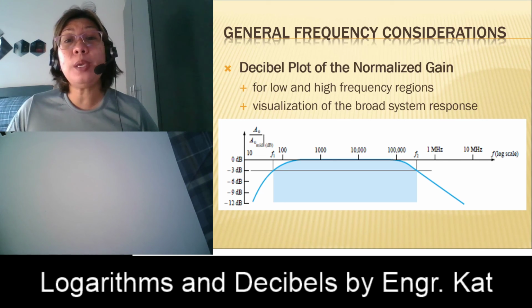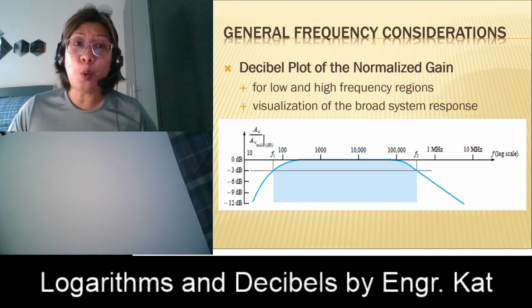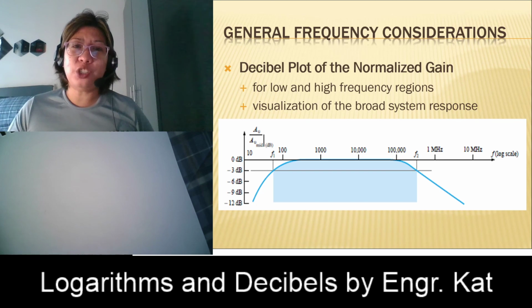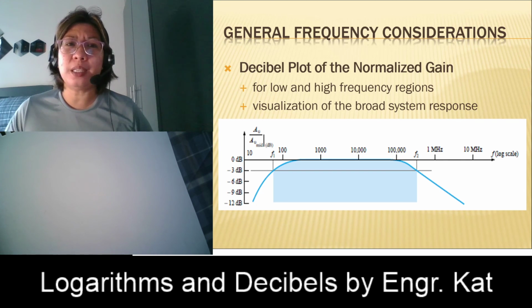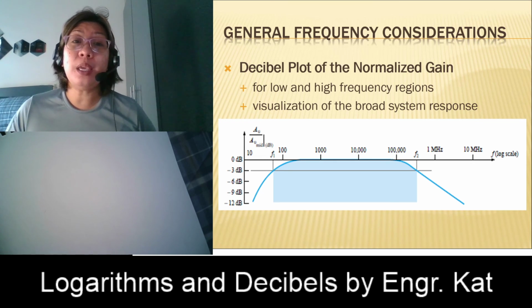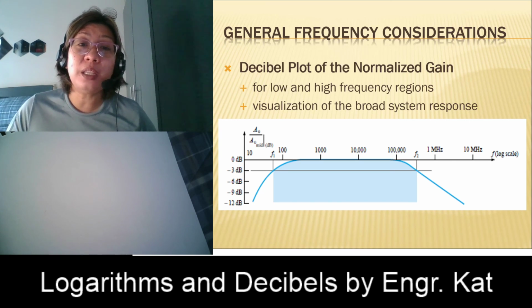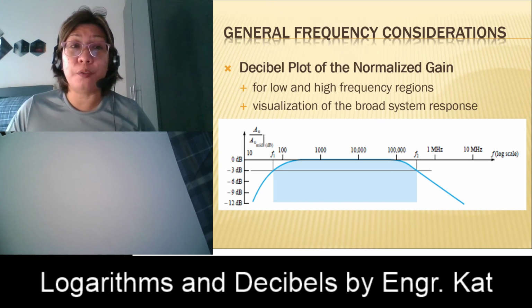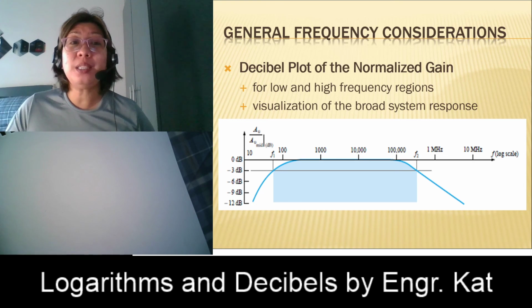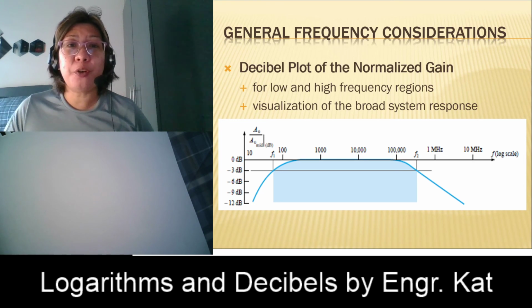So in this case, we can see that there is really a decrease compared to the upper side. So the normalized gain is just representing your frequency response below the zero level, because at mid-range we can see that you have 0 dB and it is decreasing at negative 3 dB at your cutoff, and slowly decreasing at either 6 dB per octave or 20 dB per decade. So this is just the same. However, we express this in terms of the normalized gain.